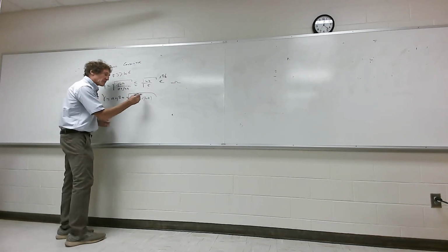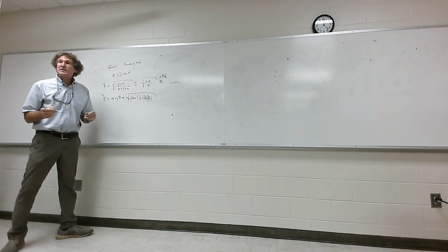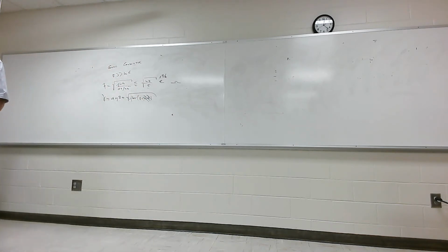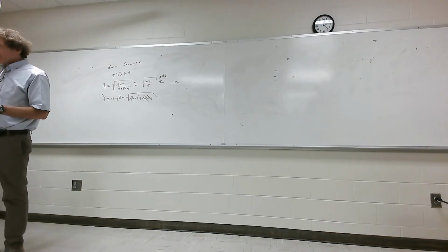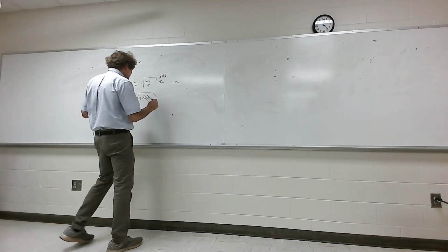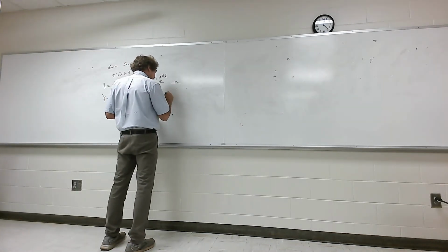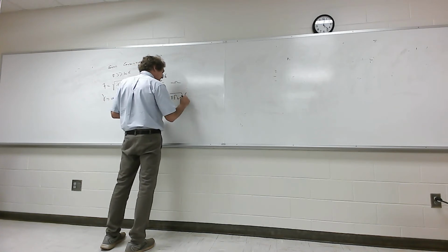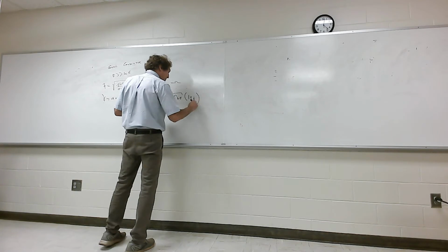This we ignore, right? We ignore that because we're assuming it's a good conductor. Now we get the square root of j. Didn't I put that up here too? Square root of j is 1 plus j over the square root of 2. Correct, class? Once we gather the terms, we find out this can be rendered as simply square root of pi f mu sigma times 1 plus j.